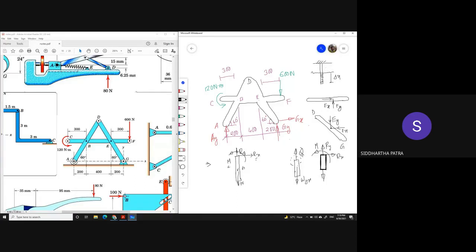In your mind you might be thinking, why am I putting Q? It should be the weight of the lower portion of the geometry. Yes, but that comes from the equations of equilibrium of the first body, I mean the first half of the body. In addition to that, the weight of this upper half, WL minus delta x, is also acting on the upper half.